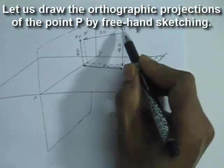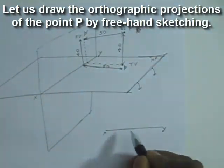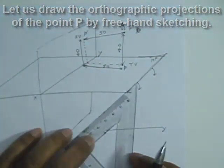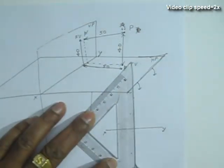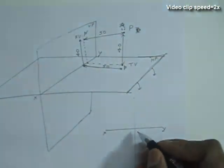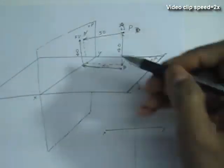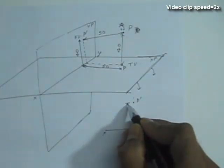So let's draw the projections by freehand. First is the reference line XY. Then we will draw a vertical line because both front view and the top view will fall on a single line, which is perpendicular to the reference line XY.